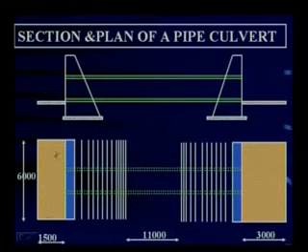This particular part is the apron which I was referring to. Apron or pitching on the upstream side. So can you get the data here from this plan? When we are making an estimate of the quantities of stone required for aprons or pitching on the upstream side, you can get the dimension from the plan here. See, this is the length of the apron, this is the width of the apron. This particular one is nothing but the head wall. As you see from the top, this is how it looks. You have a head wall on one side, the head wall is also there on the other side.